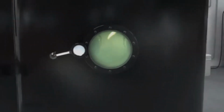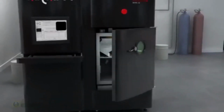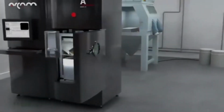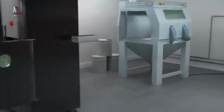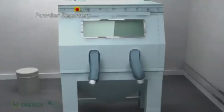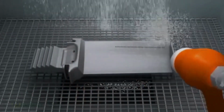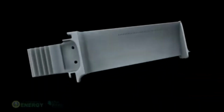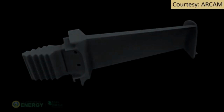After completion, the part can be taken out and it can go for a post processing of removing the powder which is adjacent to the part and got stuck to it due to high temperature of the preheating. But of course, by the abrasive jet we can really remove the powder completely and the final part will be available for us.